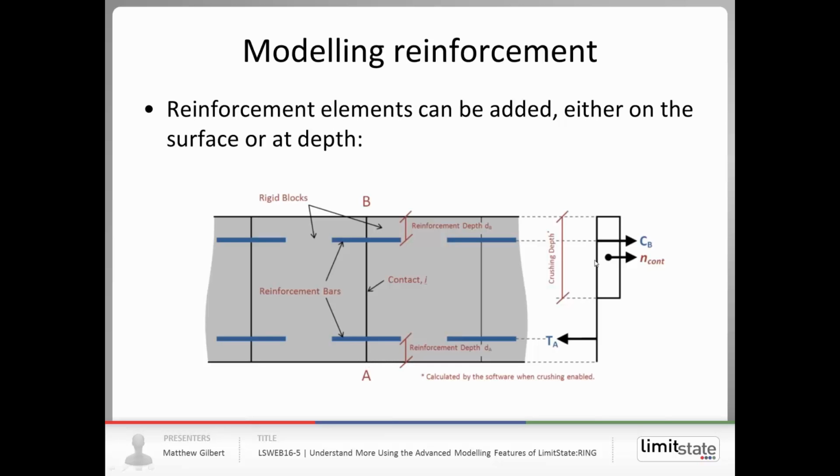In terms of the mathematical method I outlined earlier, it changes it very, very slightly. We now need to take account of a compressive and a tensile force arising from the presence of the reinforcement. But essentially the rest of the methodology stays the same.